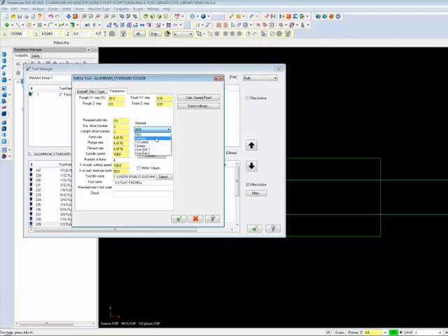The tool material is carbide. It has 3 flutes, and we'll be spinning it at 6,400 RPM. Since we have values that we got from the formulas in the catalog, we'll enter those instead of using Mastercam to calculate them. The tool feed rate is 105 inches a minute. Since the majority of our plunges are helical or ramped entries, or outside the material, we can up the plunge rate to about 75 inches per minute. And since there's no point waiting around while the tool cuts air on retracts, let's set retract speed to 200 inches a minute.